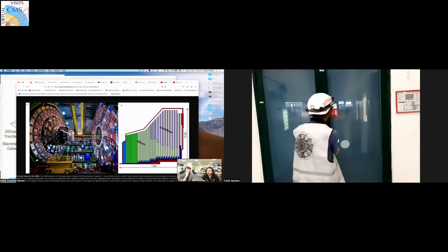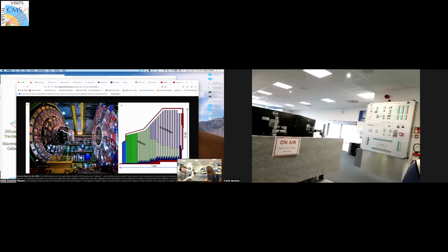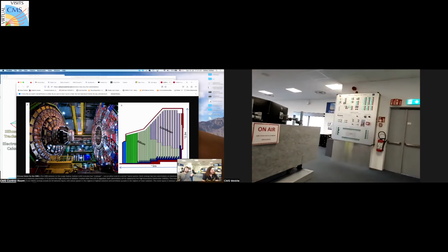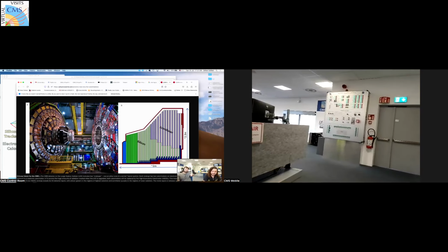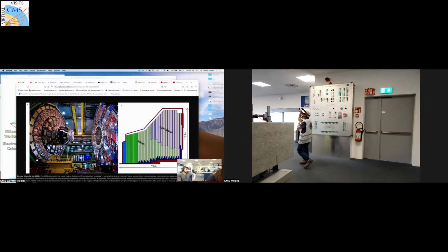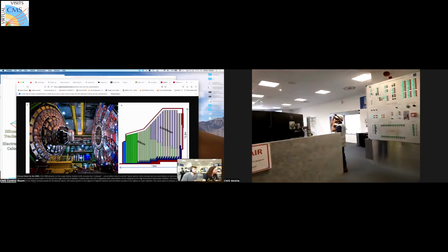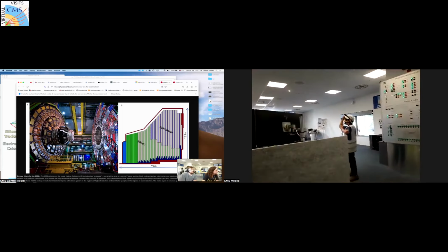Yes, of course. I'm in the control room in any case. The main complexity of going into space is that you need to add some tests that usually on the ground you do not add, because you are in a vacuum. And if you are orbiting around the Earth, you experience sunny periods and shadow periods. So these are added tests that you do.